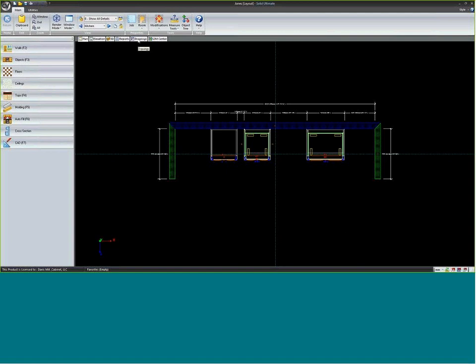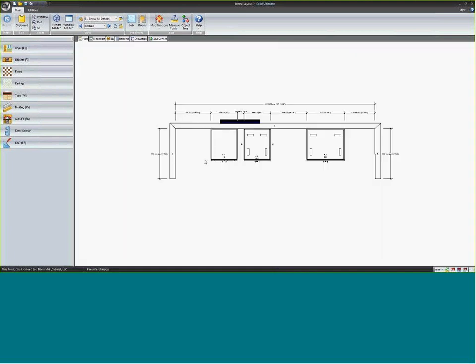Just to give you a quick demonstration of it, the way that drawings page works is that I'm going to come out to whatever view I want and take a snapshot of it. So I right-click and say to drawing. Now it makes a drawing of this item. What I've done there is made what's called a scene, it's just a snapshot of my screen.